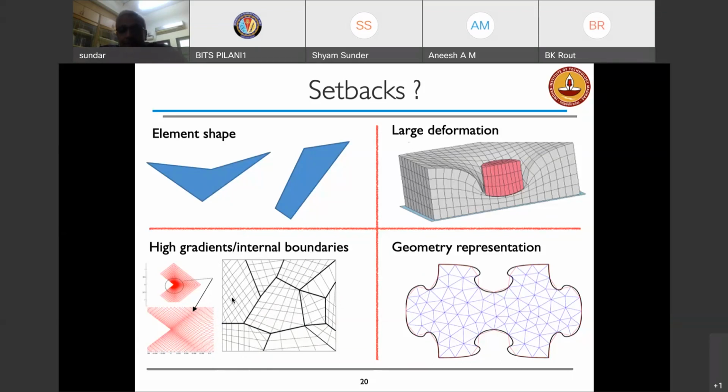And since these polycrystal materials have different elastic modulus, our knowledge on elasticity tells us that the points where these grains intersect are the likely sources of high stress concentrations. And high stress concentrations are the points where it's likely to start a damage to evolve. The damage can then become a crack, and then it really becomes computationally intensive